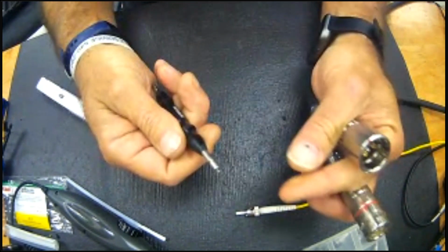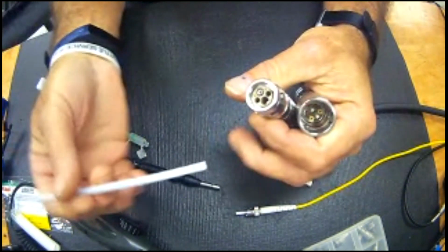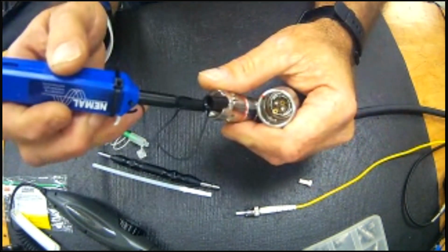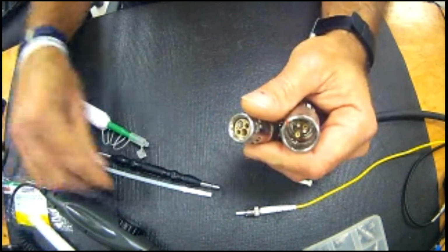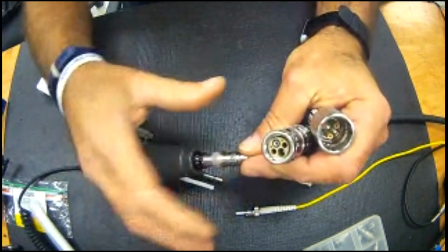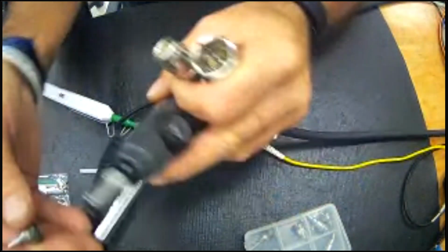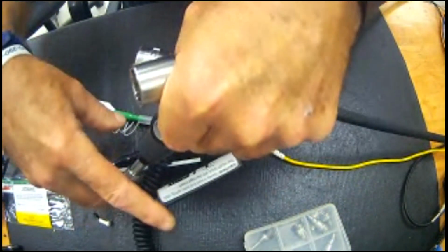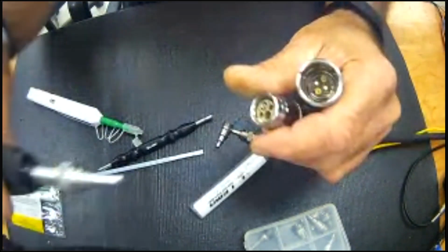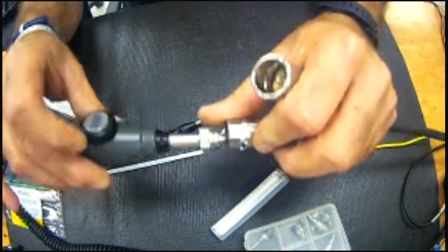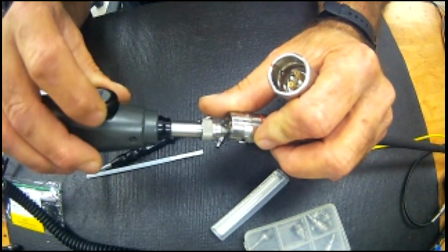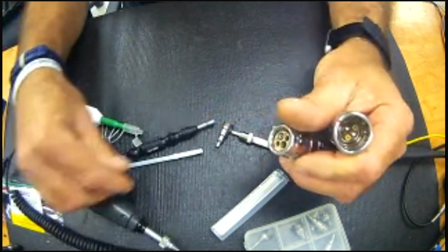There you've got your alignment sleeve in your hand. Now you'd have the advantage. You can use a one-click cleaner, snap, snap, to clean the contact. You can switch over to the tip that is made specifically for 2 millimeter contacts, reaching down inside the connector, visually inspecting it.